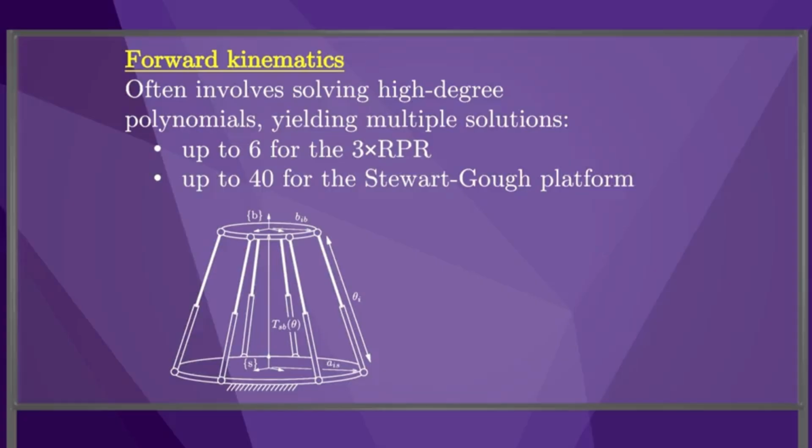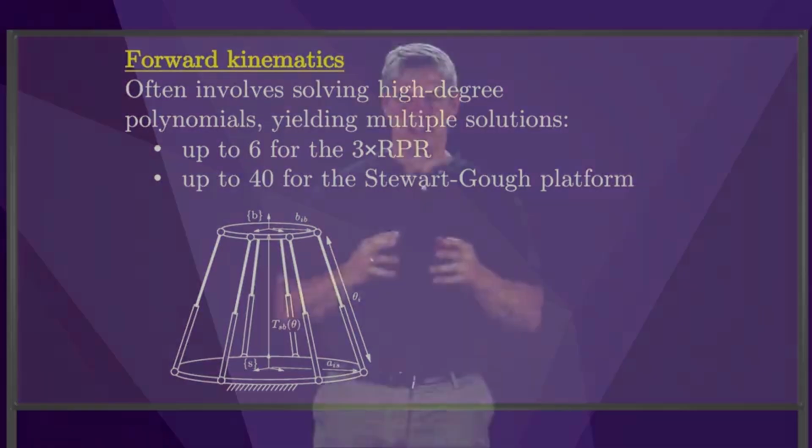In practice, it is common to use iterative numerical methods with a nearby solution as an initial guess, similar to the Newton-Raphson method we developed for the inverse kinematics of open chains. In this video, I have given you a quick summary of the topics of Chapter 7, which itself is a quick summary of the kinematic analysis of closed-chain robots. The design and analysis of closed-chain robots is an active research field, but Chapter 7 should give you a good idea of some of the key issues.